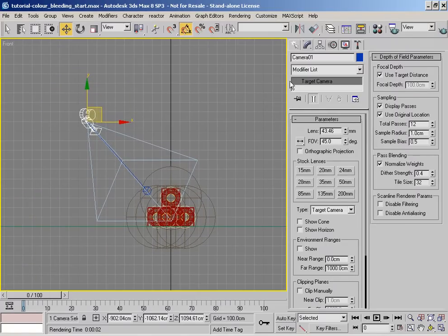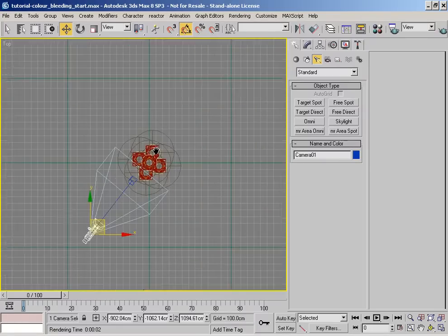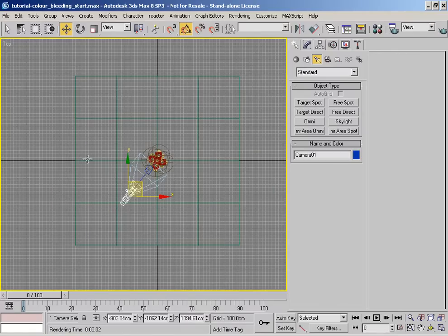the front viewport, and what I'm going to do now is I'm going to actually just go to the top. I'm going to go through and create a large hemispherical array of lights. So they're basically all pointing in like this at our number of boxes, so we get kind of like a nice diffused shadow around the edges.